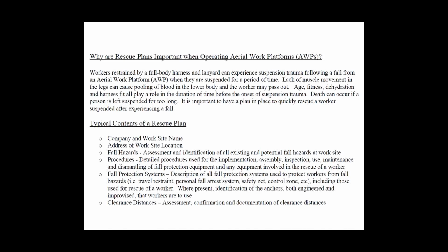Why are rescue plans important? Because if the operator is wearing a full body harness, he may be involved in suspended trauma. And based on the weight, the health, the age, and the size of the individual, you may have a limited or longer amount of time to where you may need to make a rescue. So we need to have contingencies in place. There are 3 different types of rescues that we need to think about. One would be self-rescue, the other would be assisted rescue, and the other would be professional rescue. We need to take these into consideration throughout the use of these products in the market.